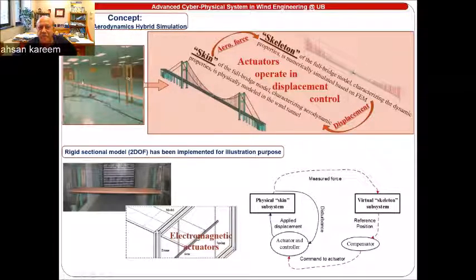which is looking at the hybrid simulation of the aerodynamics of a bridge, where the shape is in the wind tunnel, the skeleton is behind on a computer program, and they talk to each other at time steps. When the shape changes, it changes the load, and iteratively they work together. And I think they have demonstrated not a 3D bridge model, but a 2 degree of freedom system, to show that this approach, using a virtual skeleton and a physical skin, can help you do the things together. Otherwise, you don't have to make a very sophisticated model, which we would have to make otherwise.